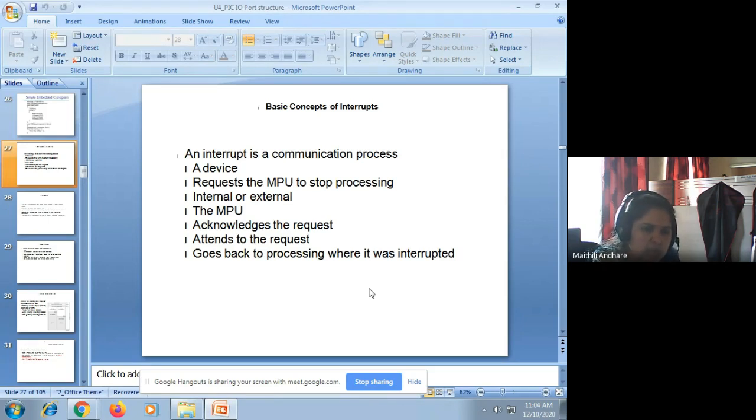Here also these two operations are performed by the timer, but the pre-scaling facility is available in the PIC microcontroller, which is not available in the 8051 microcontroller. So what do you mean by pre-scaling? By using a particular scaling factor you can increase the speed as well as the delay generation. So that is the beauty of the timer available in the PIC microcontroller.